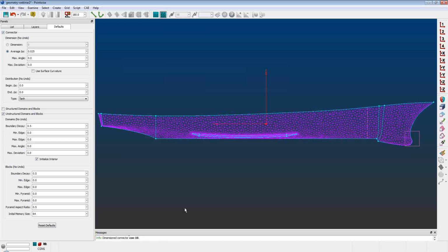So you can undo this process even though you may have gotten out of Pointwise and gotten back in, so the undo command doesn't work. But you can remove the hole just by removing the trimming curves, and the underlying surface will still be there. Does that help? I see. So you can modify the cut and remove the cut. Yeah, you can remove the existing cut and then make a new one, because the underlying surface, that hull surface without the hole, is still there. It's hidden right now, and there's just a trim surface built on top of it that has the hole cut out of it.